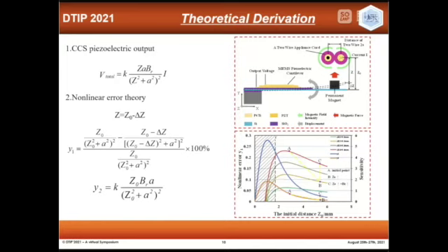At this point, the error will be decreased, followed by a significant reduction of the sensitivity. Point C indicates the state after increasing the magnetic induction on the basis of point B. After this process, from point A to the final point C, the error can be decreased while maintaining good sensitivity.